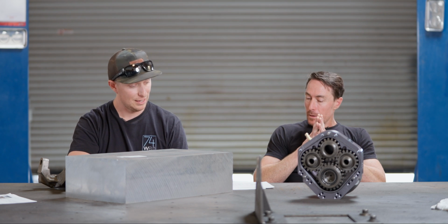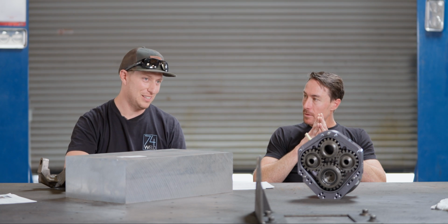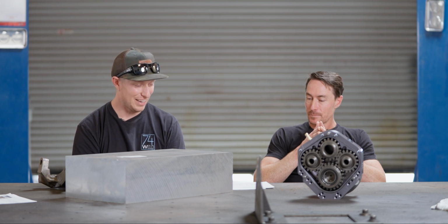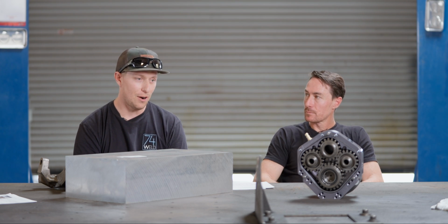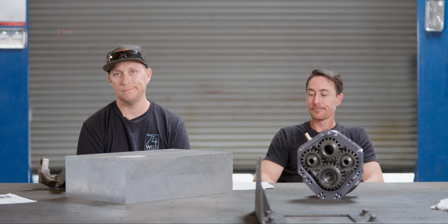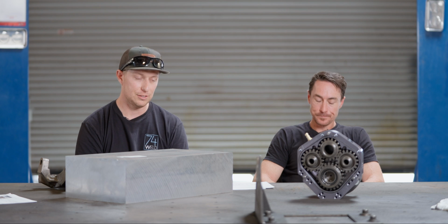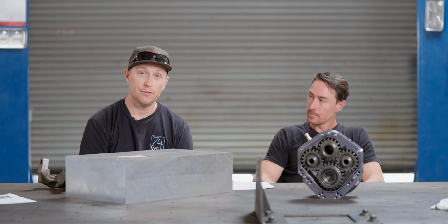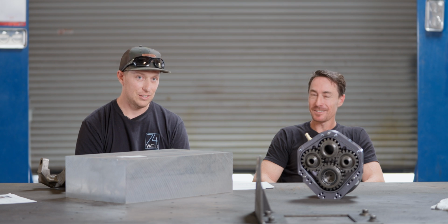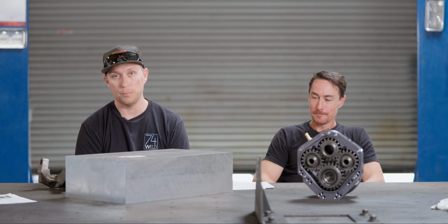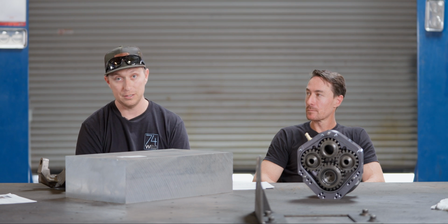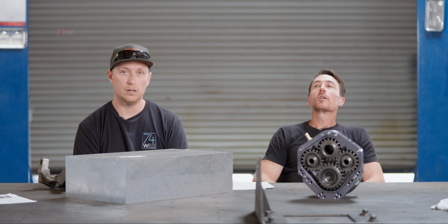It's one thing to note, since we are in kind of a nuanced area, that if you go on MatWeb, which is kind of a dictionary of material properties, and you look up, say, 4130 chromoly, you're going to get like 12 different options. A reason for that is you can have the same chemical composition, and you're going to have different material properties depending on how it's been worked, how it's been heat treated.